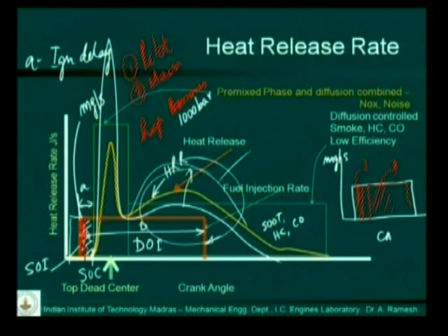To give you a feel for the time, we were looking at SI engines where we had about 10 milliseconds for injection. Then GDI engine where we have something like 1 to 2 milliseconds for injection came down. Whereas in the diesel engine, the first injection could be something like 200 microseconds. So we have gone down in scale to extremely low times.